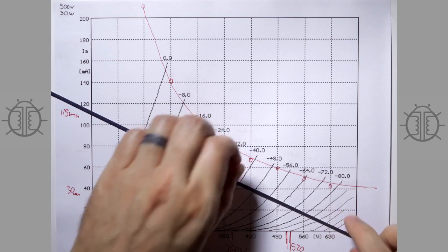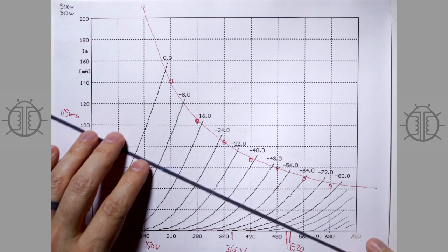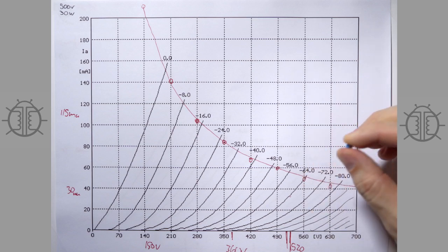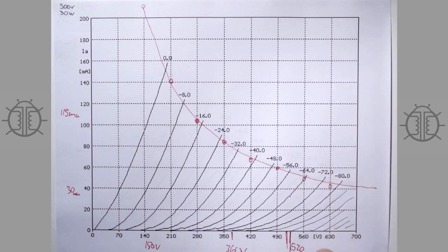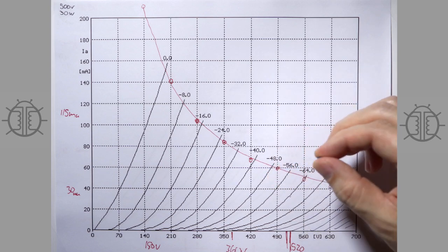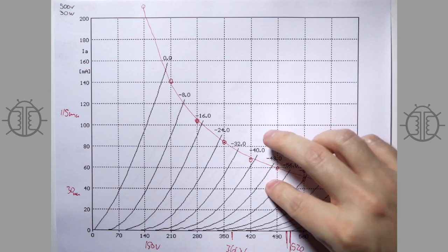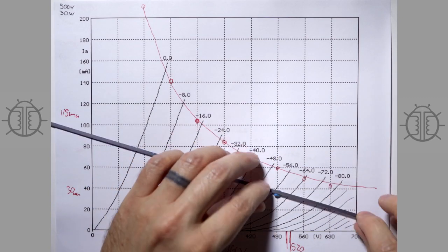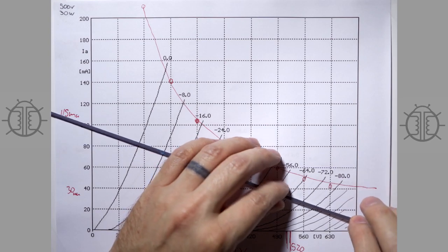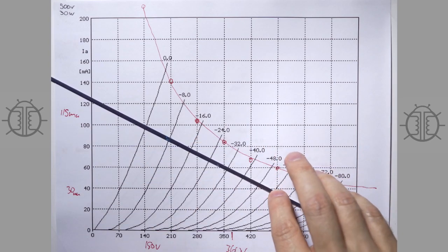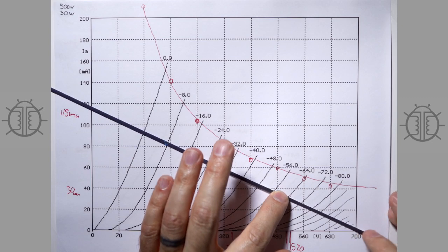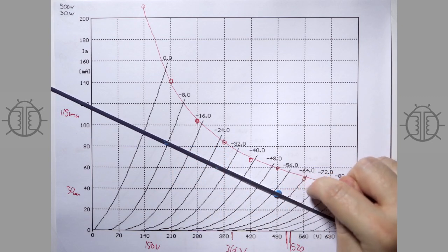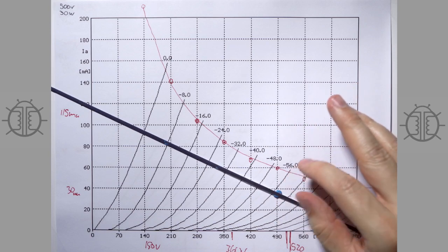So, for instance, let's do a Class AB operating point. So the first thing we'll do is we'll go up in voltage for our operating point. Let's go all the way up to, 500 volts is the max. So let's do 490 or whatever. We'll start here. And let's just ballpark it for now. We'll do maybe a load line kind of like this, right? Now, we're at negative 57 odd volts here on the grid.